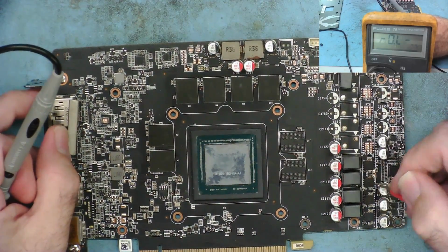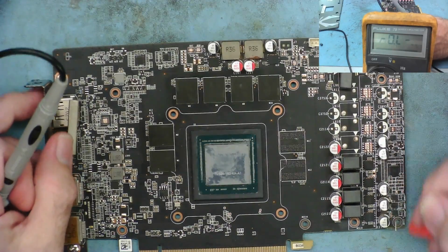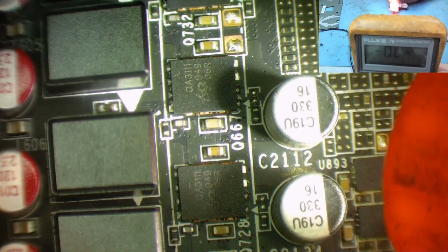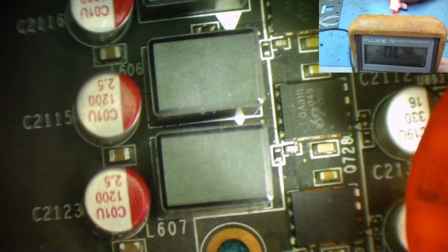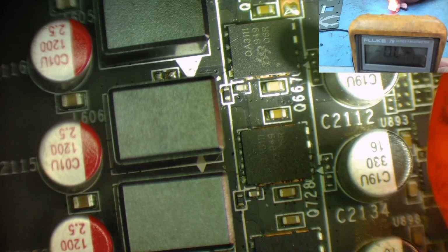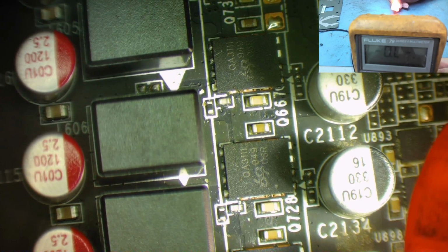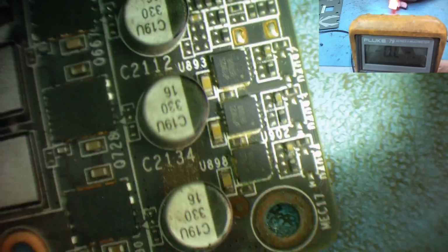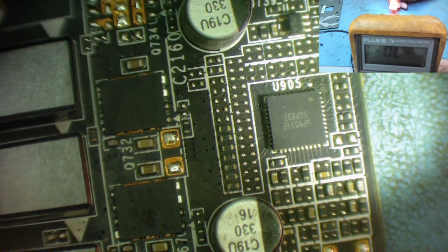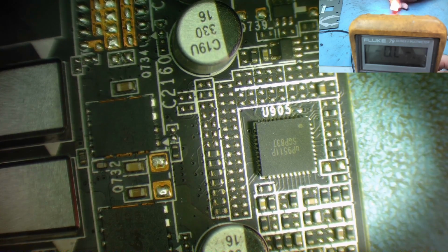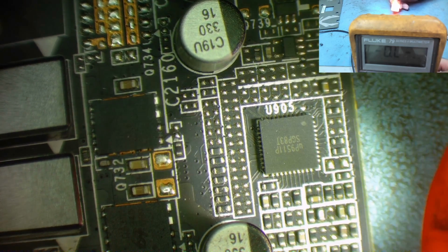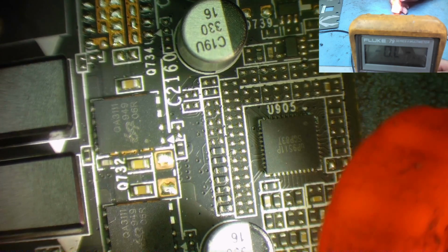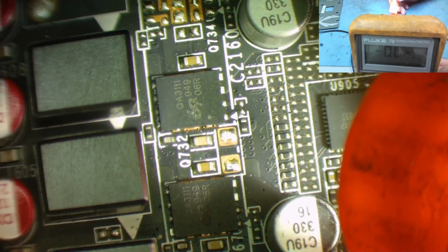This doesn't have individual MOSFETs, but it has these driver chips here. So let's zoom in on these. In fact, let's use the microscope and see what these actually are. You can see that we have a part number QA3111. So that's the part number, then some more numbers. I'm assuming the first part is actually the part number. And then here we have this chip, UP9511P. So I'm fairly confident this is going to be the VRM controller, and these may be dual MOSFETs or they may be drivers.